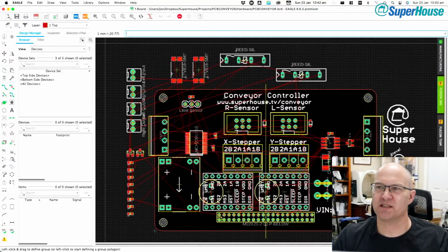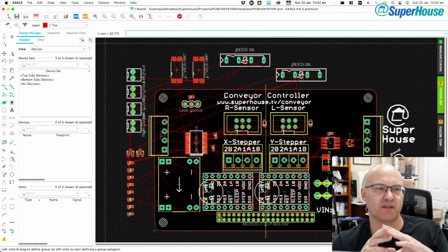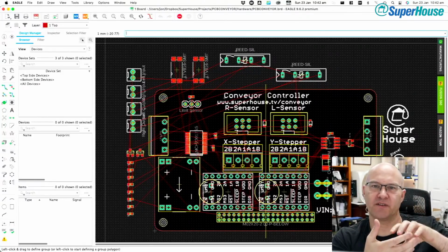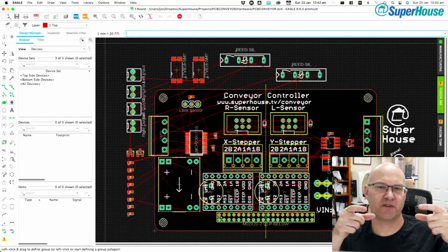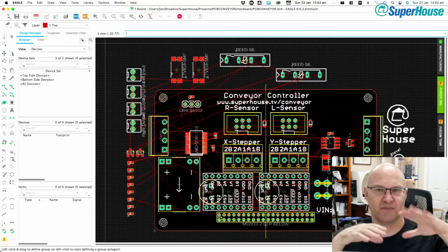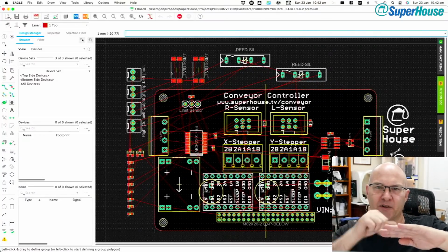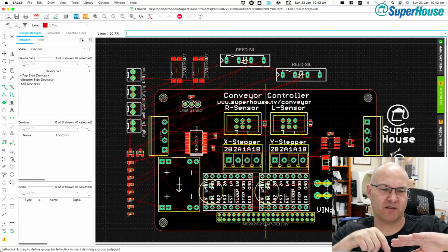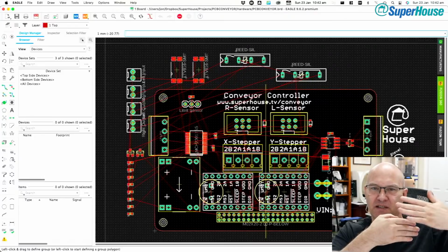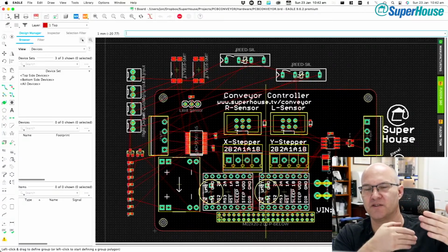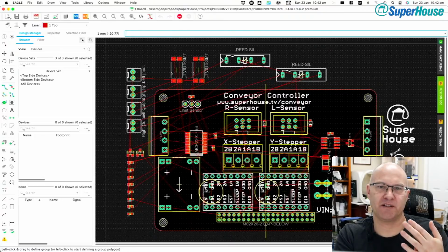The point of this is the board. What I'm going to do is make a 3D printed enclosure that will go on the front of the conveyor system that will hold the touchscreen at about a 45-degree angle. Basically, the idea is I want to be able to walk up to the conveyor, have a keypad on it, and type in 54, go, and then have the conveyor belt width adjust to suit a 54mm PCB. So I want a touchscreen interface on it.